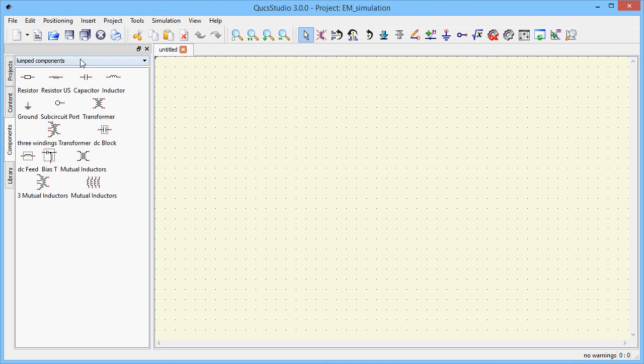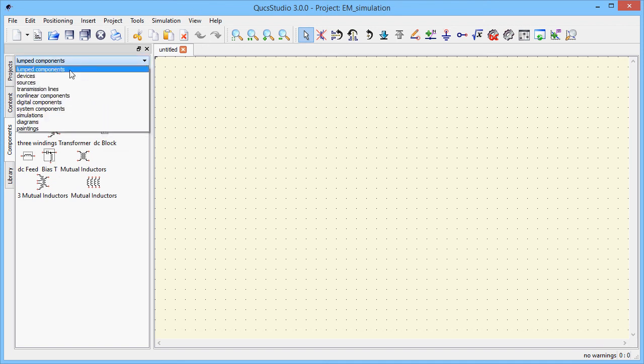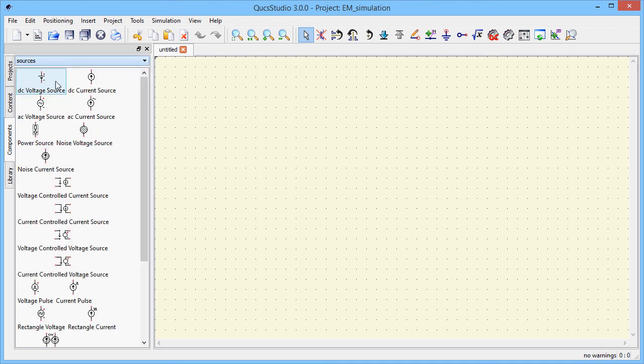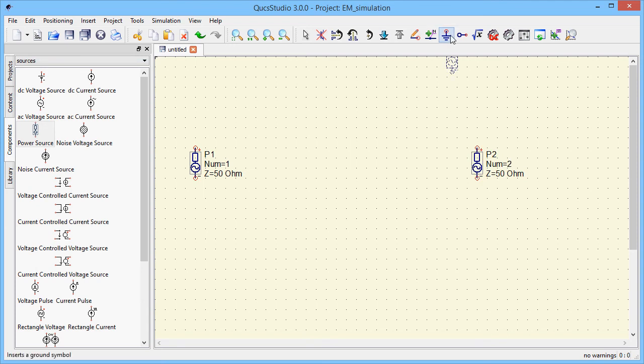Now let's perform a simple electromagnetic field simulation. First we build a stub filter with an open quarter wave transmission line. This is done with the schematic editor, because the results of the circuit simulation should be compared with the field simulation.